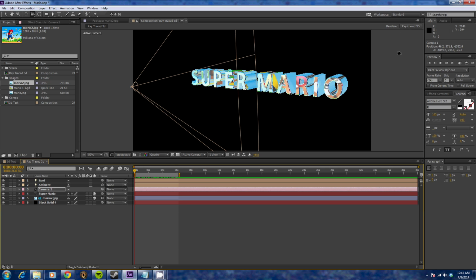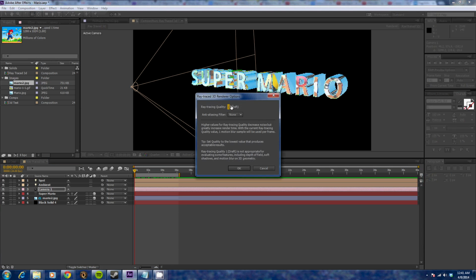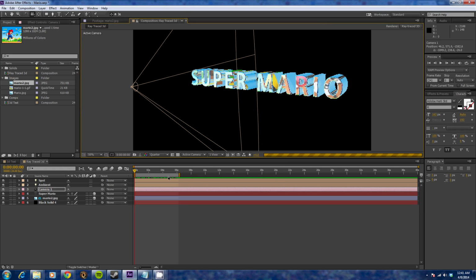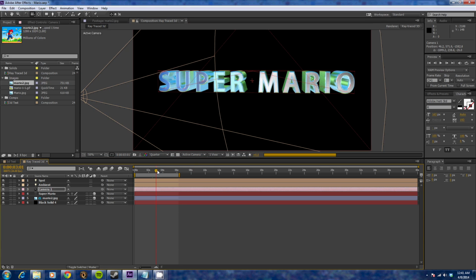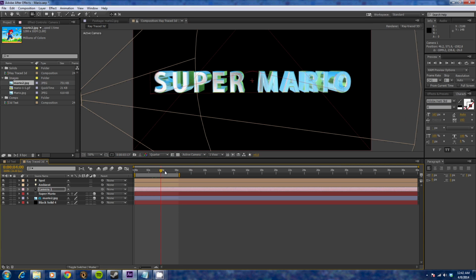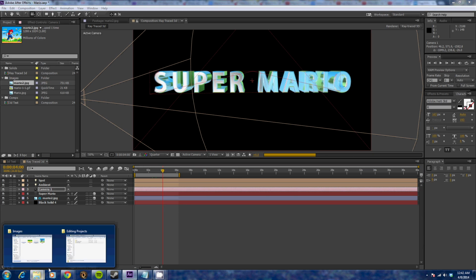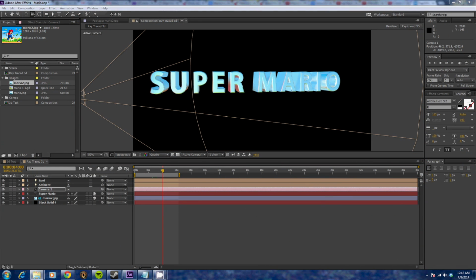And before you want to render out, you actually can control click on this again and bring it up, let's just say to 20 to get some idea, some quality with the ray trace, because right now we're working with the lowest possible quality and it still looks pretty cool. So you do that, and now your computer will freak out every time you move. But you can see how much more quality this picture is now. And to have an idea of what this looks like,